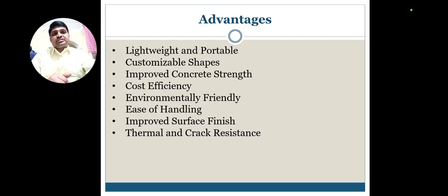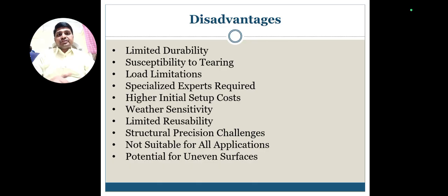So these are the advantages, and among the disadvantages, limited durability, susceptibility to tearing, limitations, specialized experts required, and higher initial setup cost. Skilled persons are required for the setting, and there is weather sensitivity and limited reusability, because the textile material will be destroyed over different usages, and structural precision challenges will be there. So there are a number of disadvantages for the fabric formwork.